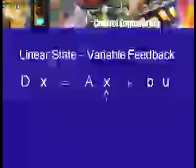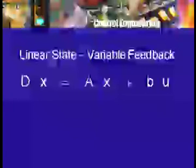Now, if you look at the solution, the part of the solution which depends only on the initial values of x, then that will consist of exponentials whose exponents are the characteristic values or the eigenvalues of A. So, suppose that this set of equations is the set of equations for a control system, and my matrix A is such that the characteristic values are not good enough.